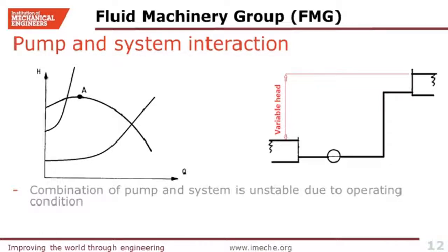By transferring liquid from the tank in suction to the tank in discharge at constant flow rate, the suction static pressure is decreasing and discharge static pressure is increasing. So at the start, the combination of pump and system curve could be seen, say, as stable, but after a while, the intersection point between the system curve and performance curve moves to the left-hand side of the hump, and as soon as the system head increases to the maximum pump head, the pump can no longer provide the necessary head and is likely to fall into that cyclic variation in head and flow rate.